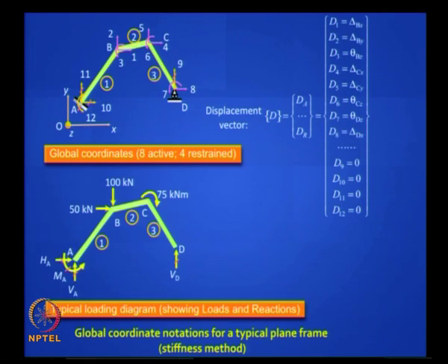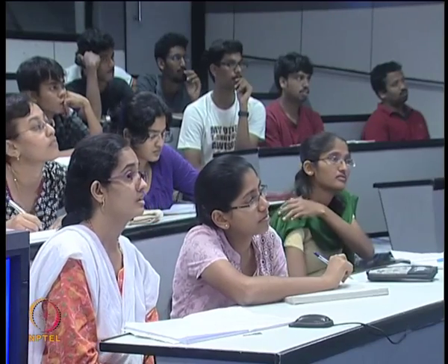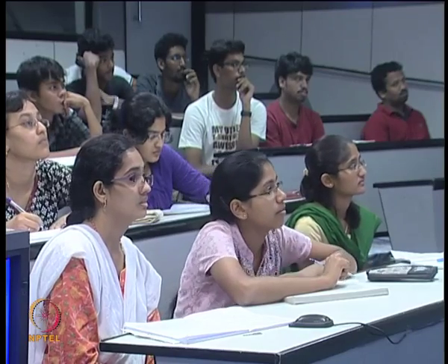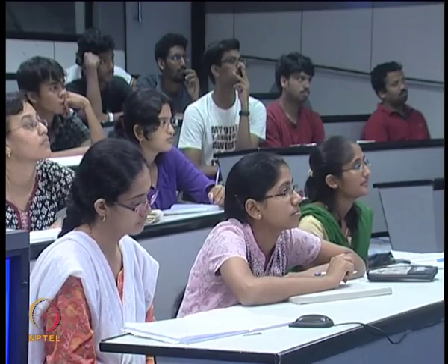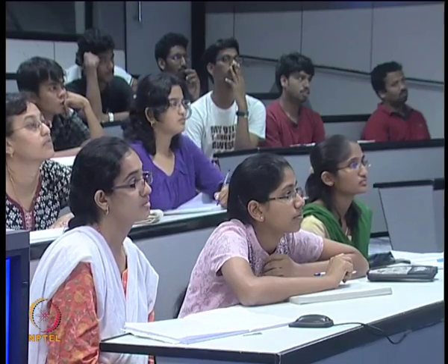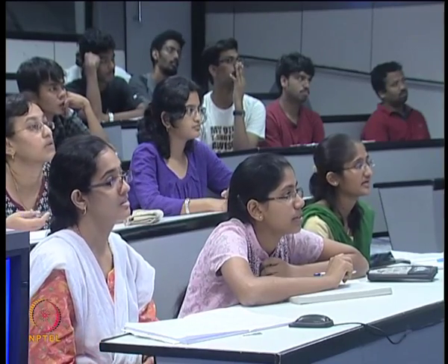Let us look at a problem where you have some loads applied. How will you write down the force vector? So I have in this problem 3 loads. So what would you call 50 kilonewton? What is plus 50 kilonewton? You should talk in the language of the coordinates. F1 is 50 kilonewton. What is 100 kilonewton? Minus. Yeah, so F2 is minus 100.